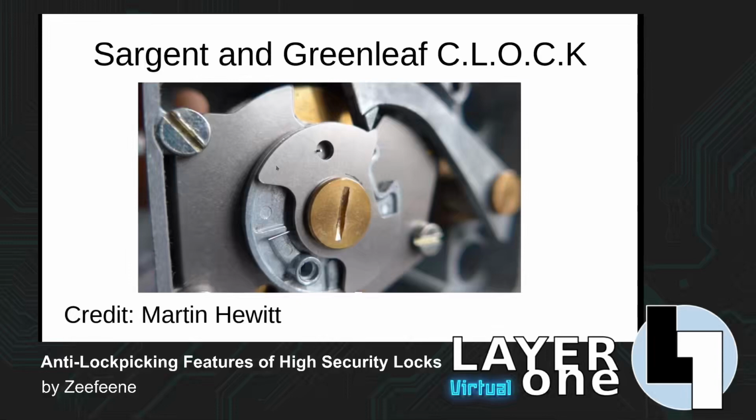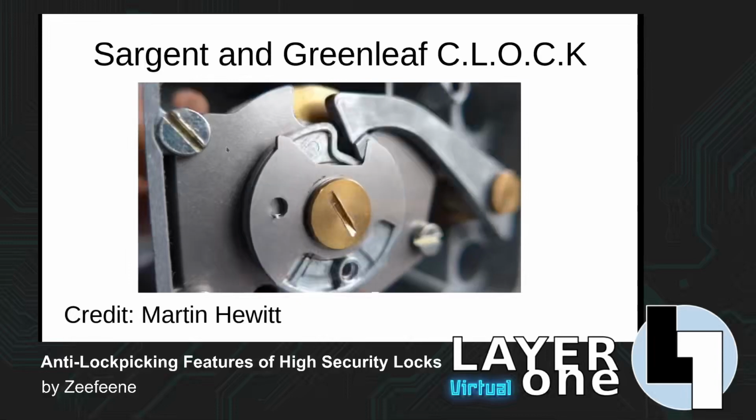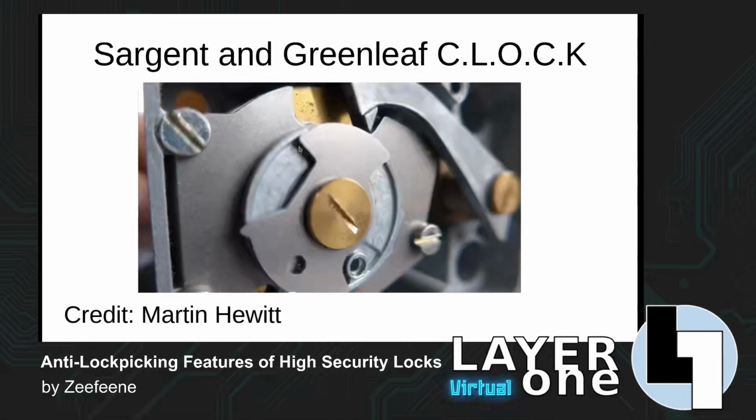a moment. And again, if we're very lucky and everything is perfectly aligned, well then the lever nose will be able to drop into that gate, and it will prevent this clever cam mechanism from then immediately concealing the gate again. And if we did not get everything correct, well then what happens is that the lever touches down against the wheels for a moment of a second, and then the sprung element that is released immediately pushes it back out of the way, and we get back into this position here where there is no gate and we have no information.